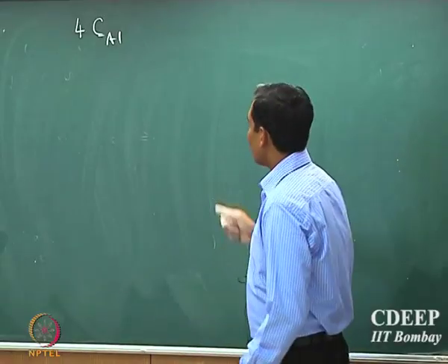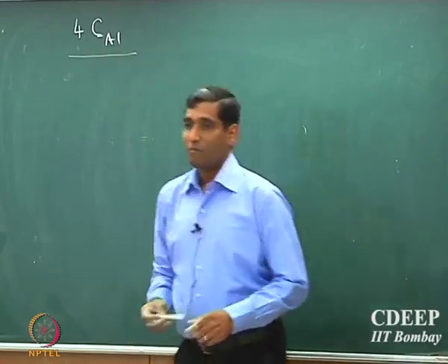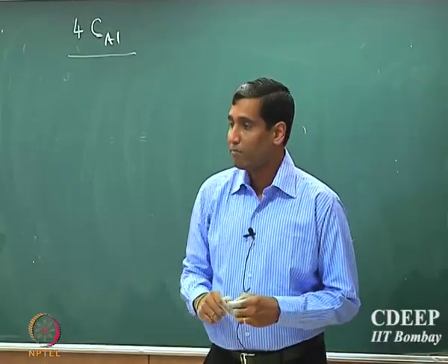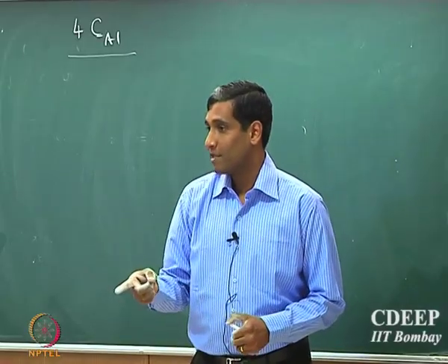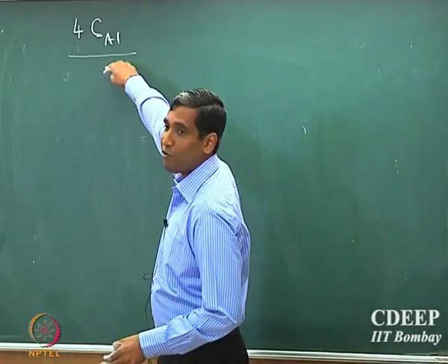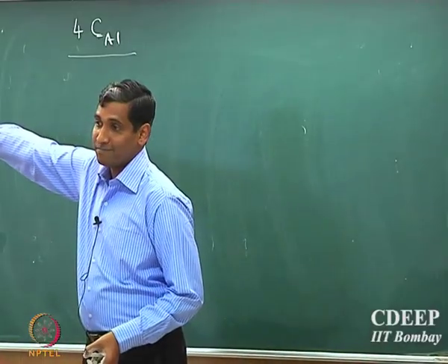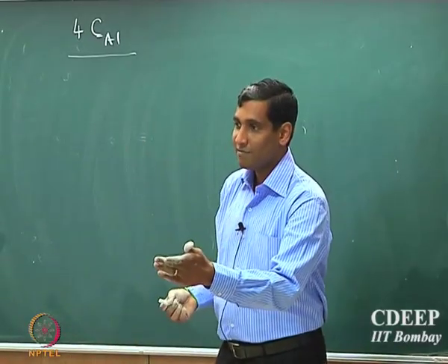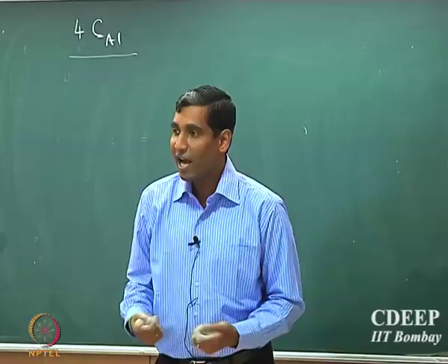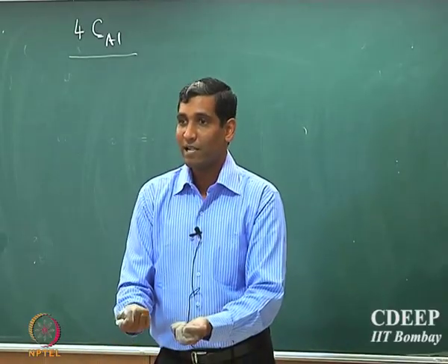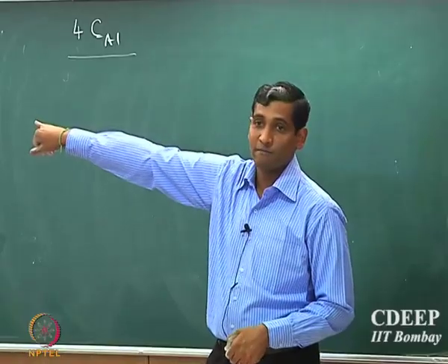Correct. So the first thing is that if you assume that the transport, the velocity effects because of the concentration change is negligible, right? So you can still have incompressible. If you have 4 times the species that is added, you can still, by tweaking the velocity, have a higher velocity flow, have gradients, play with the gradients du by dx and du by dy, and still maintain an incompressible fluid. Okay. So incompressible does not necessarily mean that the concentration does not affect the velocity.